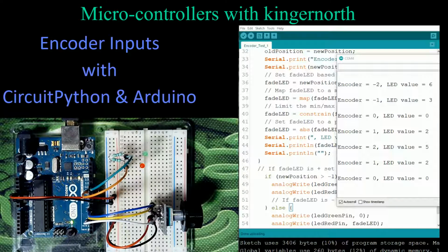Now you might be saying, well, where is this useful to me? Well, it doesn't have to be lights. If it's in your model trains, this doesn't have to be light. If you're trying to supply DC power to a motor, this could be forward and reverse and adjustable speed. So we've actually given you the ability to have adjustable speeds in here, which is really kind of nice. It's a nice little feature, and it just adds to the credibility of whatever you're running. So now I can bring a motor from a stop, make it go forward, and then I can stop it, and I can then make a motor go backwards. This is a basic throttle control.